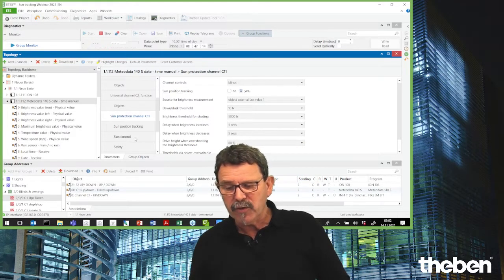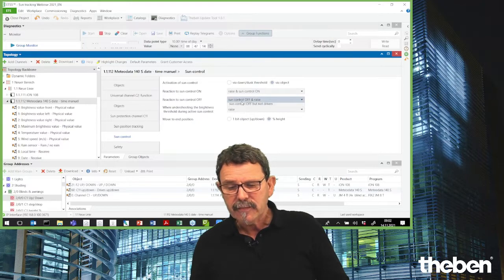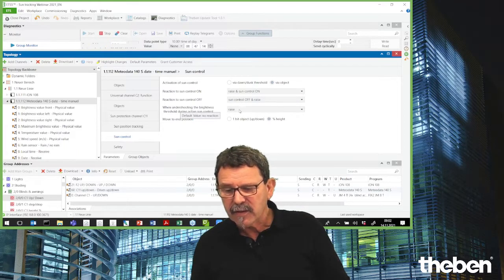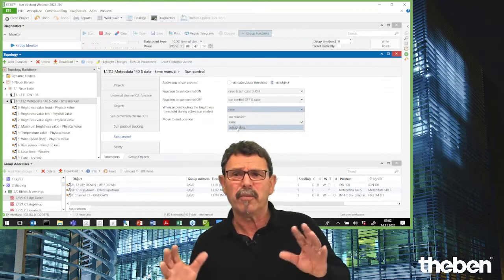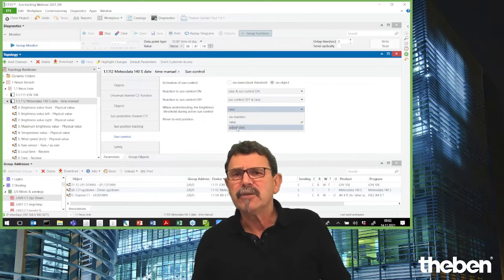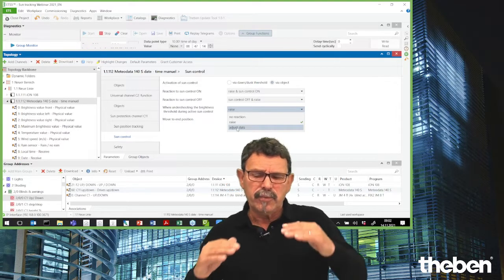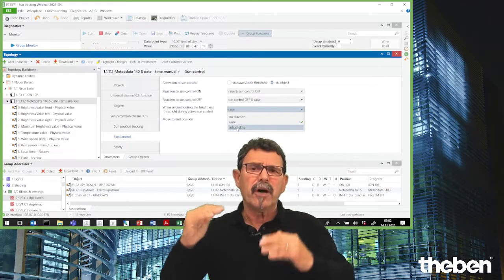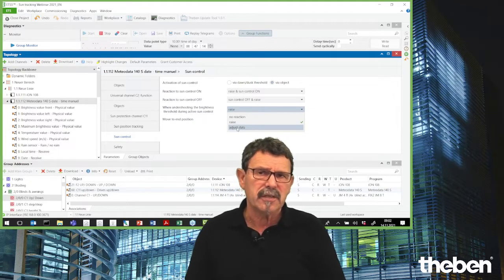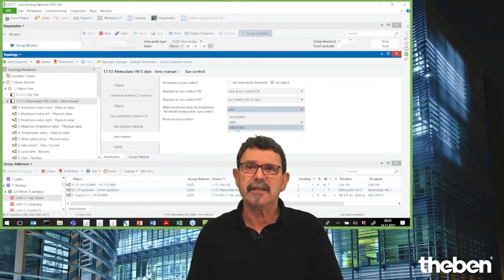And if you are underneath this level, then, for instance, you can rise. So this is the option what you can do. Or probably if you don't want to have these ups and downs, however, during the daytime you do have a cloudy day, then the real value is always swiveling around your preset value of 10,000 lux or so. So then the blinds or the slats are running up and down. However, when the sun is there, it runs down. When the sun is off and the clouds are there, it's running up.